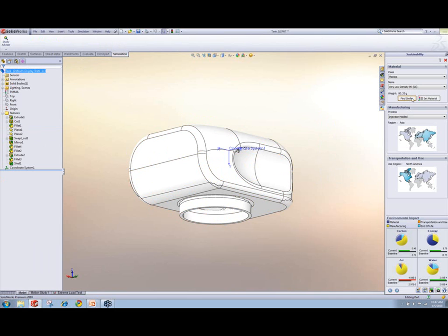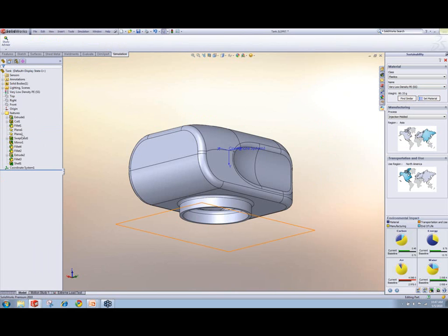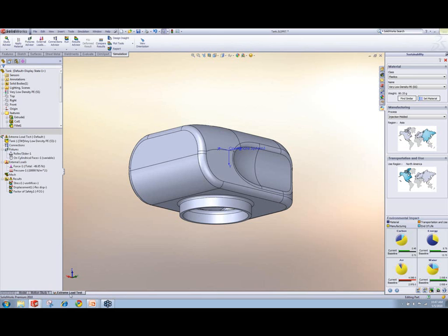I want to go back to the sustainability and click on set material, and this will change my material over to what I've selected now, which is the very low density PE. Now with that selected inside of my model, I want to go back and update my assembly. And you'll notice here, because sustainability, SOLIDWORKS, and simulation work hand in hand, this has also updated my material as well. And I want to go in and update components and rerun the study.